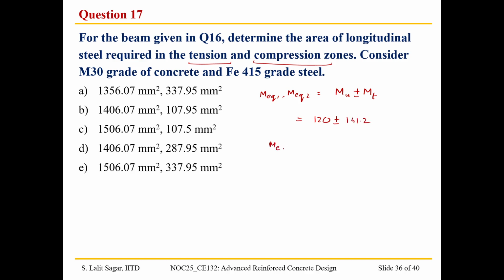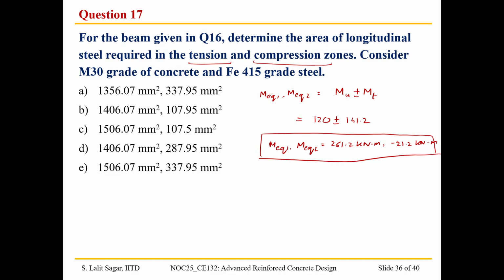So MEQ1 and MEQ2 would be 261.2 kilonewton meter and minus 21.2 kilonewton meter. These are the equivalent moments for which we need to carry out the design.